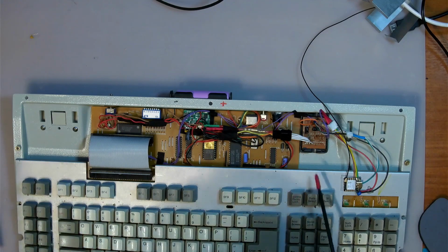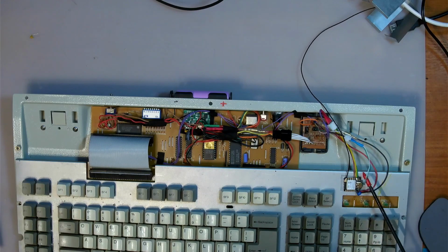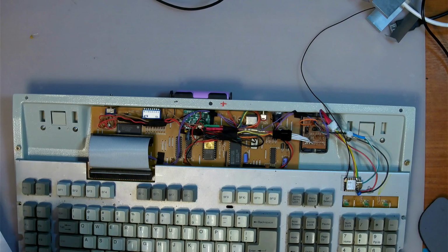So, as I said, what I've actually done is I soldered some wires. Now, on the bottom of this little board are two little pads, D plus and D minus. So I went to the internet and looked at some images. I couldn't remember which one was green and which one was white. I've seen them before in different places. Got some green and white wire, and I looked it up. And the first image I looked at on the internet was that white was D plus and green was D minus. So I thought, okay.